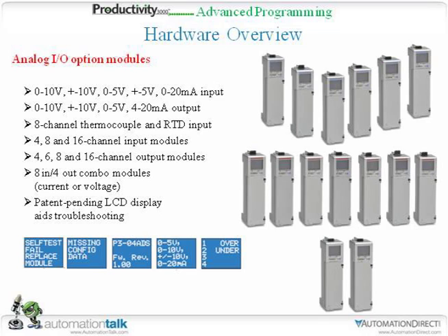If you've used PLCs, you've obviously used some discrete. Everybody wants to get into the more complicated, more powerful modules and instructions. I love those analogs with the displays on them. Those are awesome. Maybe we should mention real quick, it's a patent pending LCD display. I made use of it when I was setting up the demonstration to double check that my temperature and distance probes were giving me the correct values, and that I had the right channel selected.